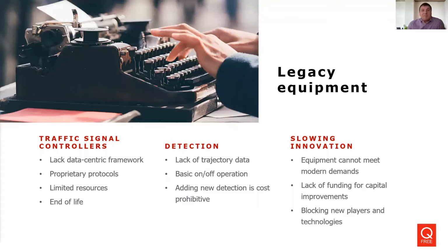Talking about equipment specifically in the field, specifically signal controllers and detection. Signal controllers, the older ones are lacking the technology to process tons of data. A lot of them also lack resources. So an older controller that was being sold up to 3 or 4 years ago might have had limited time on the processor, limited memory available to the software that would operate the signal. So if a customer or maybe a vendor or whoever wants to add some cool new coordination feature to reduce transition time, there's a possibility you'd have to steal from other functionalities. So maybe for that build of software, it had half the detectors the previous build had, because all those resources used up by half the detectors in the software are now being reappropriated to a coordination thing.